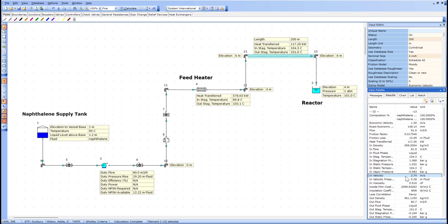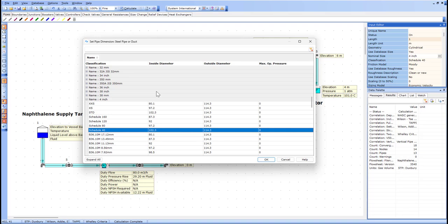We also need to weigh pressure loss, pump duty, operating cost, future capacity, and fluid-specific risks. For molten naphthalene, thermal behavior matters just as much as hydraulics. A larger pipe reduces friction loss but increases surface area and fluid inventory, leading to greater heat loss and a higher risk of cooling during low flow or stagnant conditions. A smaller pipe does the opposite. The best choice balances hydraulic performance, efficiency, cost, and reliable thermal operation. We'll proceed with the 6-inch, 154.1 millimeters pipe.